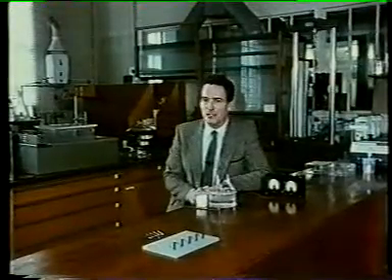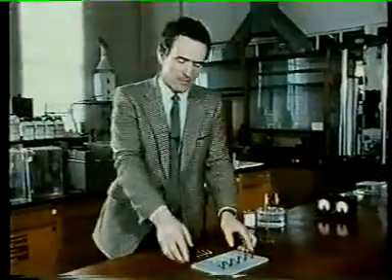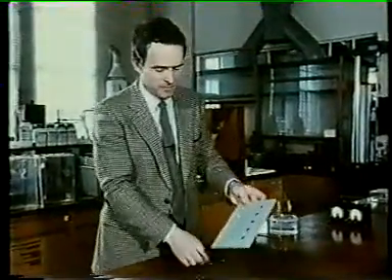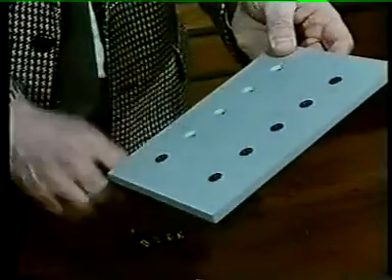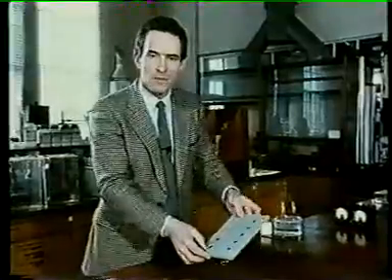And we're not just talking about something that happens in the laboratory. Think about a steel fastener in contact with an aluminium panel. Put them in a wet and possibly salty environment, corrosion is a certainty. In practice, such processes usually occur quite slowly during the normal life of an aircraft, and a great deal can be done at the design stage to prevent them happening at all.